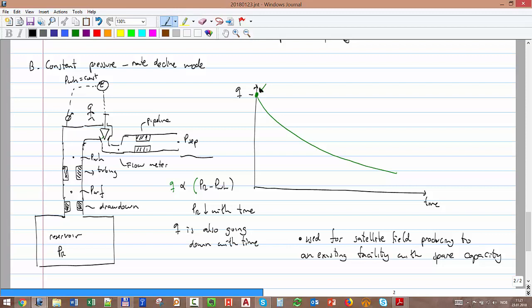Remember, if we think about the economy, it is usually always, from the point of view of revenue, to have the highest revenue or the highest production as quick as possible. So if you think about it in a very cool way, how I will get the highest revenue is just producing the field at its maximum all the time. Okay, just fully open choke. The problem is that for big fields, I will need two big processing facilities. Then the capex will be extremely high, and that will make the project non-economical.